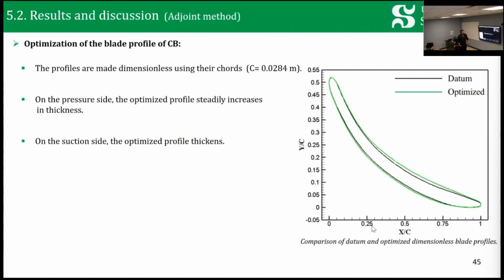This is the final shape of the initial and optimized profile. As I mentioned, it becomes thinner on both sides, but since we had bigger changes, bigger values for the pressure side, it becomes thinner on that side.